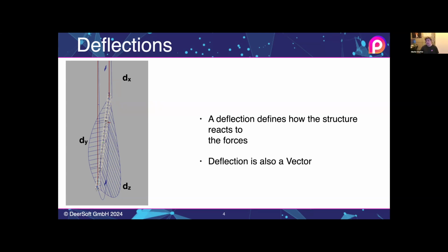And that's a really good way to check if the calculation that you're doing is good or not. For example, if you have very big deflections and maybe some truss pieces are not lining up, that's an indication that they are not connected. So the check of the deflection figure is really something that makes it simple for you to understand what's going on.